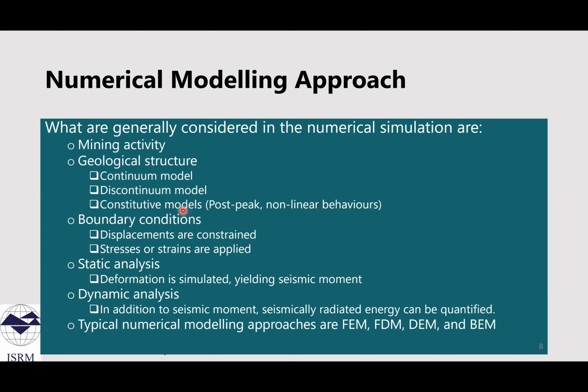After that, we need to input the physical and mechanical parameters to the model. After performing the analysis, seismic source parameters that are the same as those derived from the monitoring system can be obtained, like seismic moment, moment magnitude, and slip rate, and so on.